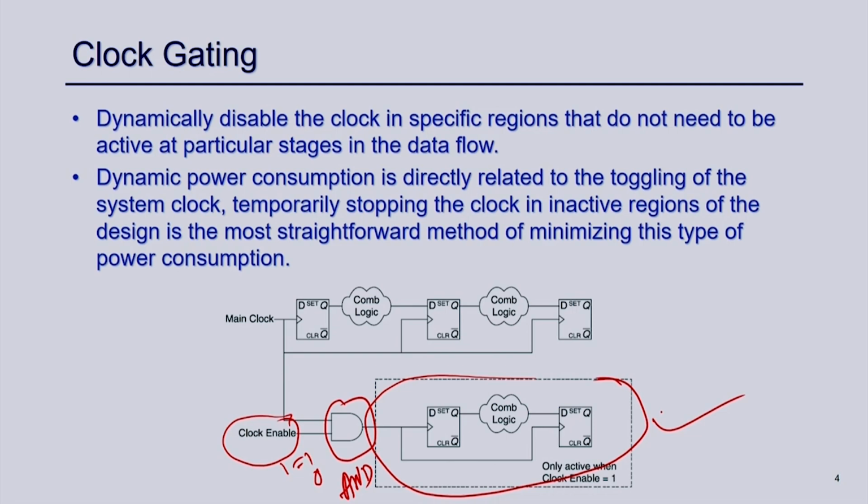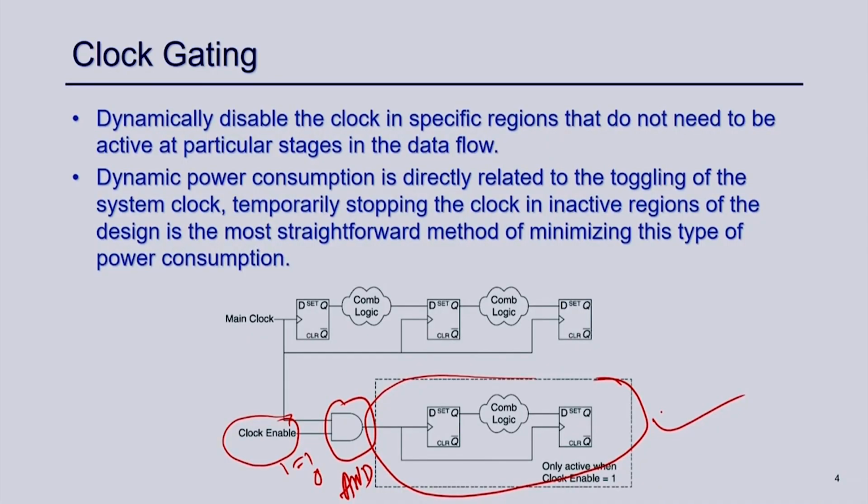As a result, the power consumption of this part of the circuit will be less, right? So, this is what is called clock gating. It is a very well-known technique, used widely specifically in ASIC targets, not for FPGA, which we will discuss in detail. For FPGA this is not an acceptable or preferable power optimization technique. We should avoid clock gating if you design something for FPGA. So, this is one technique that effectively tries to reduce the toggling, effectively reducing the value C, which is capacitance.